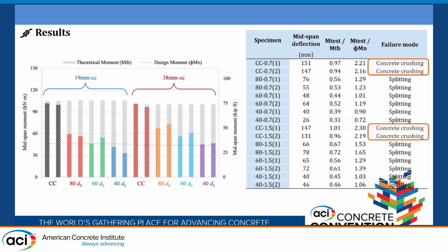But after we reviewed the strain gauges, the strain gauge was around 90%, 95% of the ultimate tensile strength. So we were almost there to be able to break the rebars in the continuous specimens. Also, the design approach, the theoretical ultimate moment versus the test moment, was almost one. So the design philosophy and design approach was good in these cases.